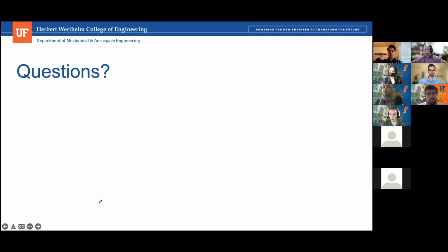So we were really researching what kind of mechanism we could use to actually output that high gear ratio that we wanted, because our PVCs were kind of heavy, and the low cost and high torque output of this design, which is a modified design of something that we found online, really came out to be just the best. So we essentially took the design from this guy's online source, modified it so it had the right pin diameter, the right torque output that we needed, the right gear ratio, and we applied it to our model.